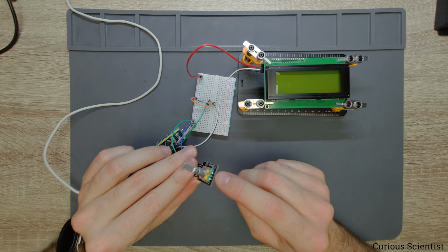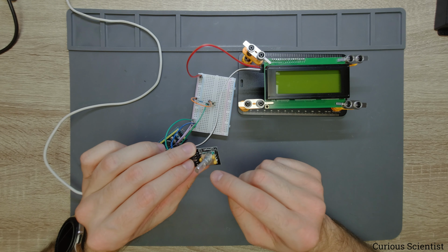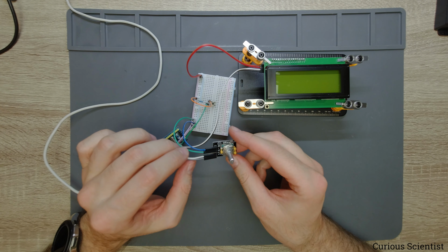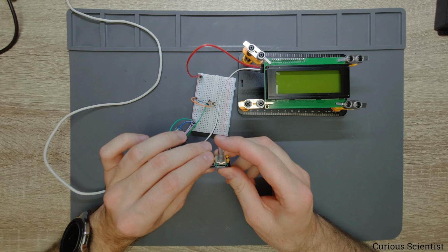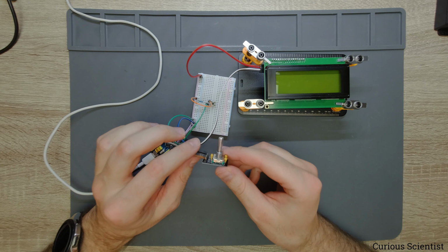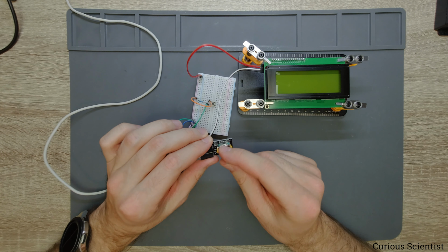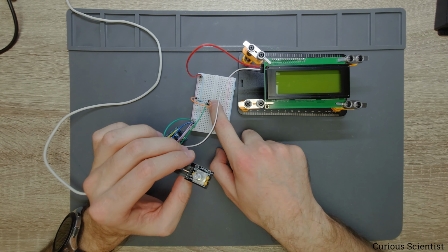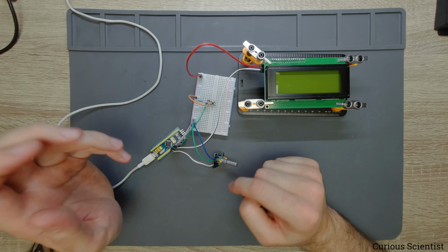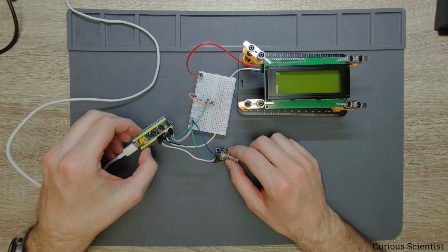And what we are going to use here is a rotary encoder, and I updated this by using 100 nanofarad capacitors between the CLK pin and the COM, and the DT pin and the COM, and also between the switch pin and the COM. But for some reason the button of this rotary encoder was not so reliable, so I just use the rotary encoder part of it, and I use a push button here to switch things.